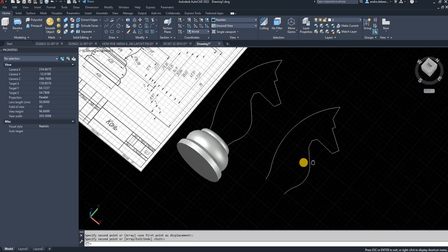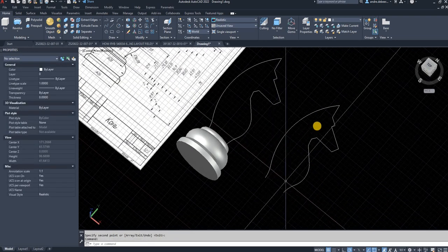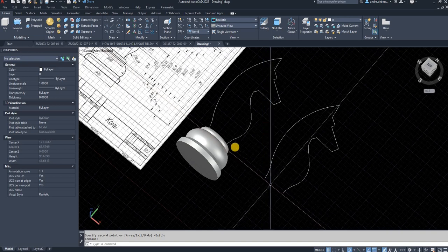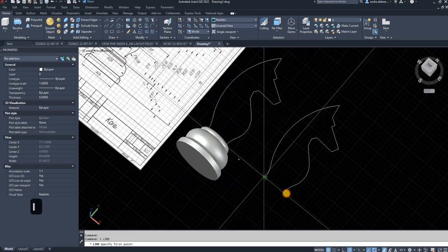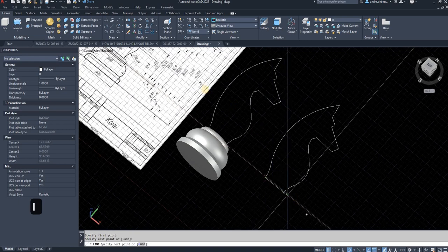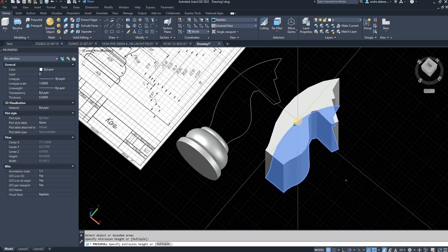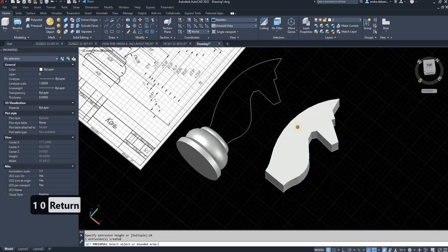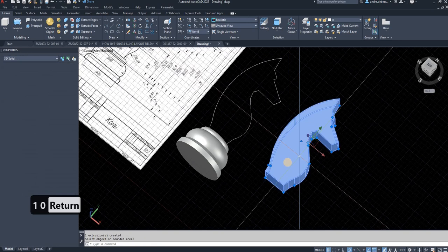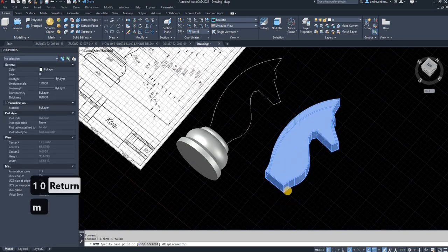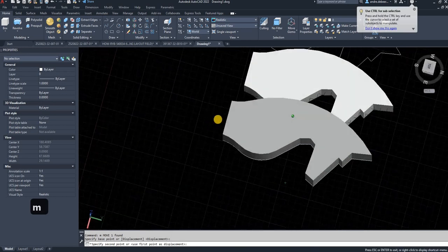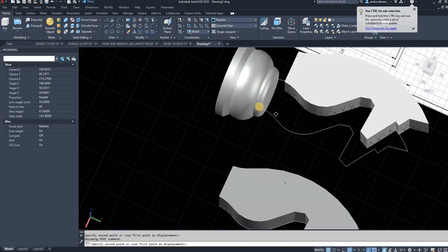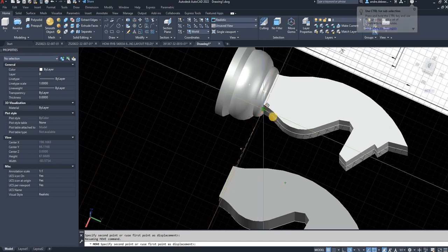The reason I'm doing this is because, as you can see, this press pull, there's no island isolated there, because that line that was here has been used to revolve the bottom piece. So I can just close there, and I can use the press pull function, 10 millimeters. Now I can move it into place. I'm going to use the center of the bottom and just move it to the point on the line that you have left here.